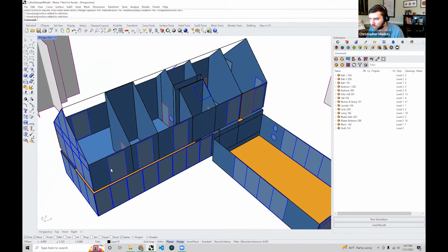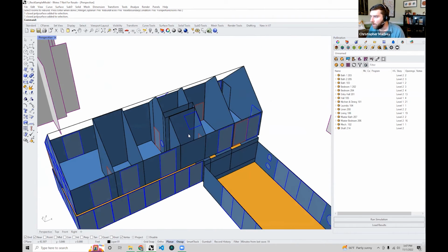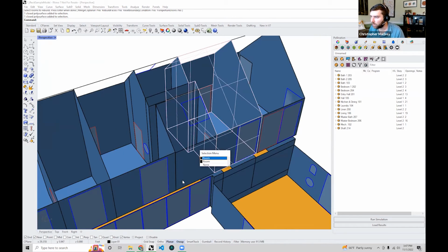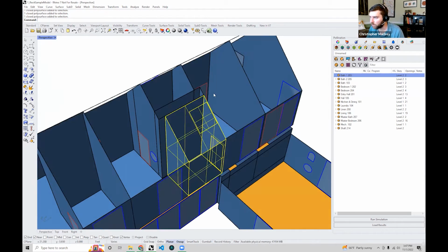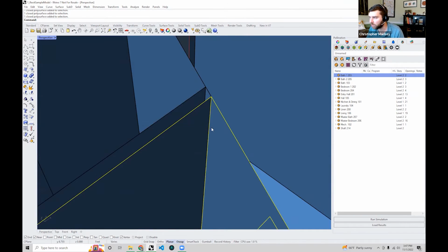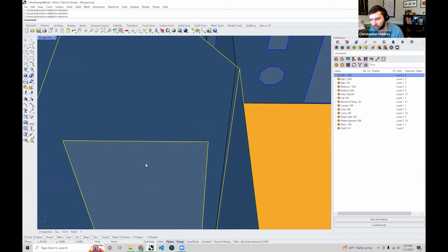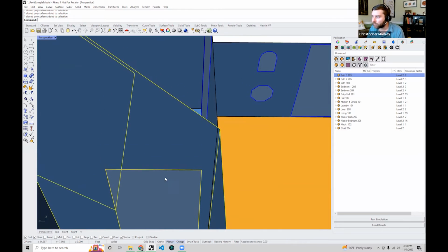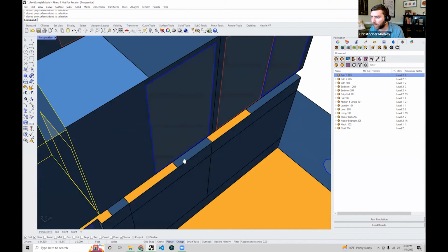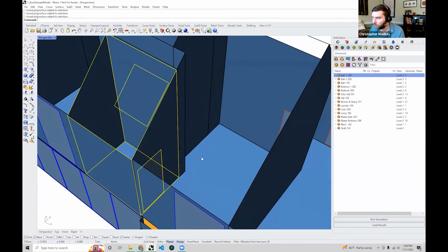For now, we solved that little sliver geometry. Let's go ahead and try to solve this little geometry that we have here, the one that was perfectly close but not completely touching. You can actually see the reason why it is this way: this room was extruded in a manner that wasn't perfectly vertical. That's a super common problem that you find in Rhino models, maybe not so much in Revit, but definitely in Rhino. People don't realize they're not extruding perfectly vertically. So in order to fix this problem, I'm going to use the native Rhino move edge command.